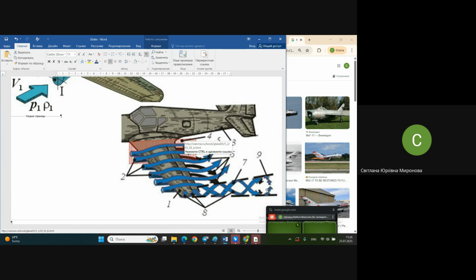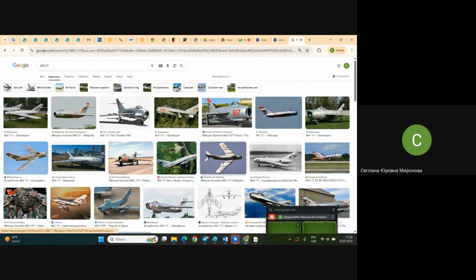Something should happen. Vortexes appear on the tips of the wing and will be responsible for additional drag, which is undesirable, of course, especially for maneuverable airplanes. Sorry, I start talking too quickly again. I hope you understood what aerodynamical fences are. Of course, not in all structures might we meet them. It's a rather specific thing, more typical for swept airplanes, for high-speed airplanes, and so on.